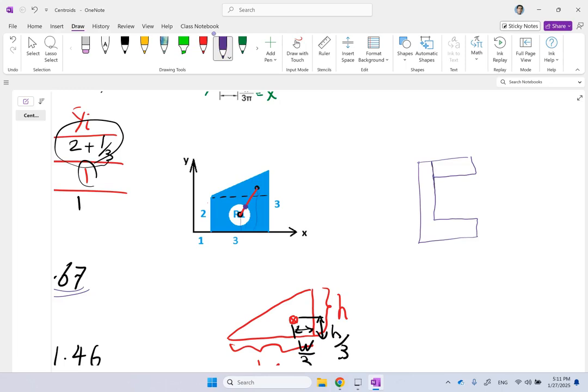So one is this rectangle, one is this one, 2, one is this bottom one, 3. And this guy has a symmetry axis, so the symmetry axis is this. So clearly it's somewhere here, but the thing is the centroid of shape 1 is there, centroids of 2 and 3 are here and here. And so it's between these two, so it is going to fall here actually. That is the centroid of the whole shape, and it is clearly outside the shaded area.